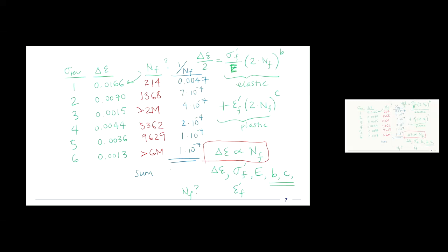If we sum all of those up, that's the damage that we get in a single block. And it comes out to be 0.0057. Right? And we can keep more digits if we want to be more precise. So that's in one block, so that's 5 seconds. We calculated our multiplier way back at the beginning. So if that's our damage for one block, we multiply that by 180 to get the full 15 minutes. And we come up with 1.0251.